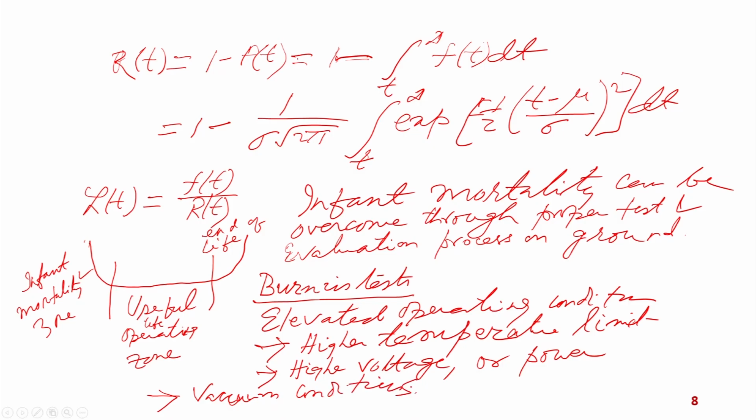So, if you do this properly, the burnout test, and keep those components which are successful, then this infant mortality can be avoided, or it can be overcome, that type of failure.